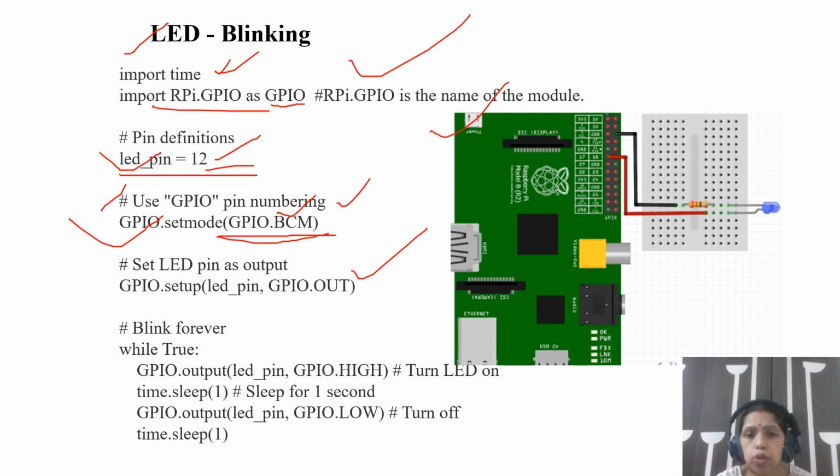I have to send the logic 1 or logic 0 through the LED. In Arduino you have seen that there is a void loop function. If the program should execute infinite times, you have to write the code in the void loop function, but here there is no concept of the void loop function, only while True. If you want to execute a set of instructions infinitely, you have to write the instructions under the while True syntax. This process will continue infinite times. That's why True.